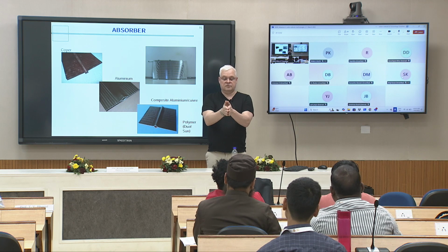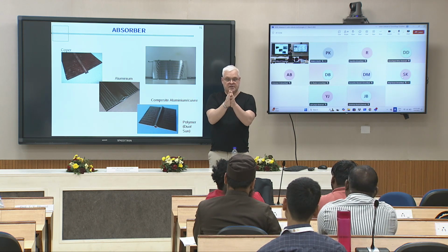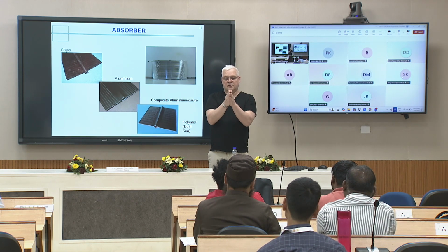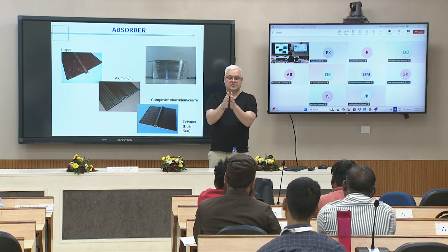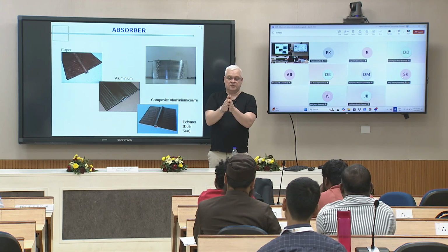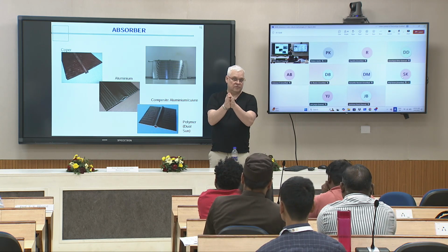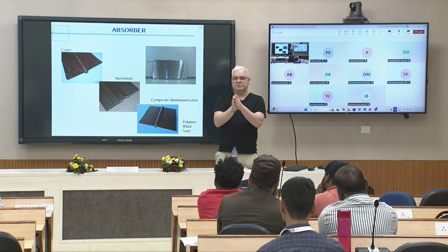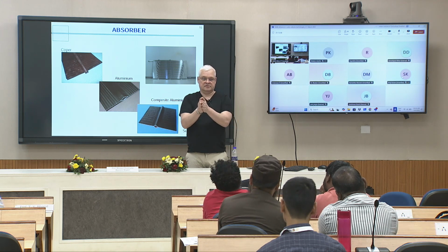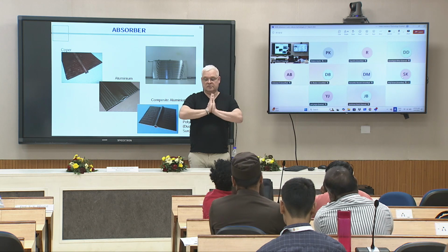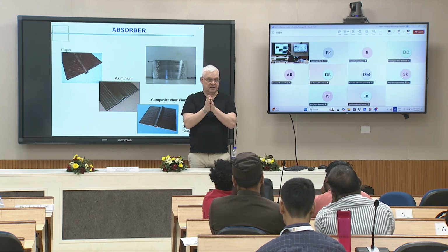Then you put the two foils of aluminum together and you heat. When you heat, there is a melt, a connection of the aluminum between the two foils, except in the places where there is the ink. There is no mixing where there is ink.